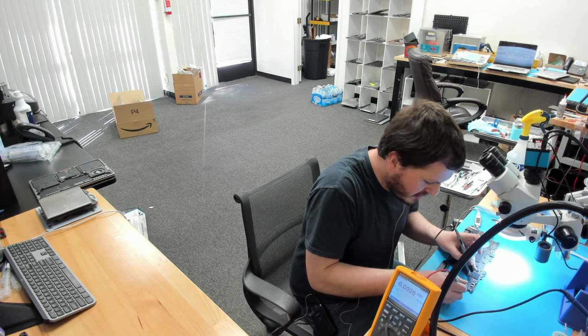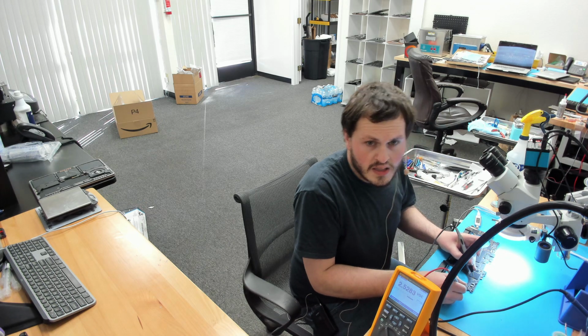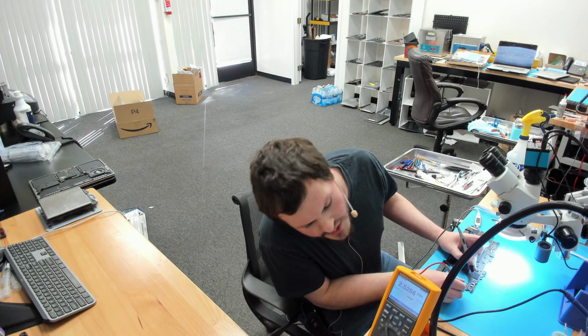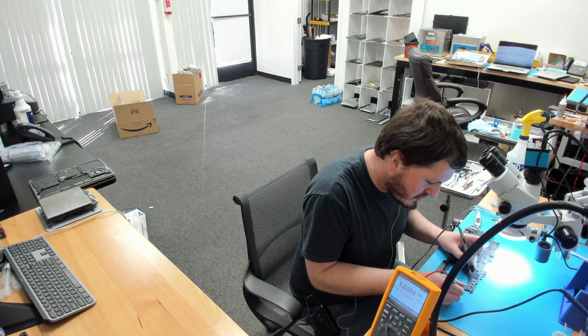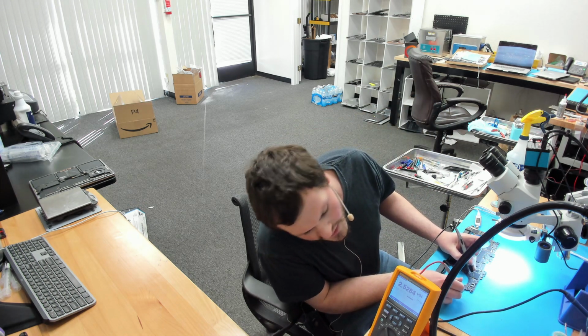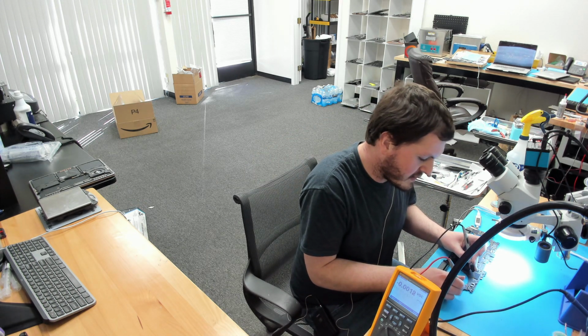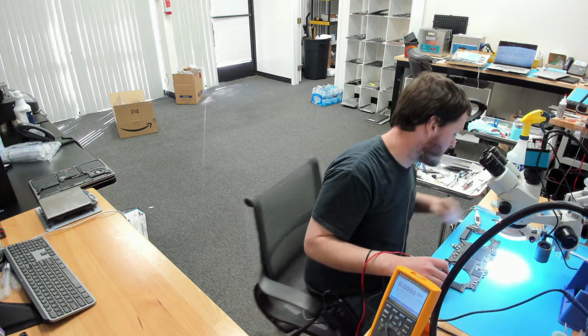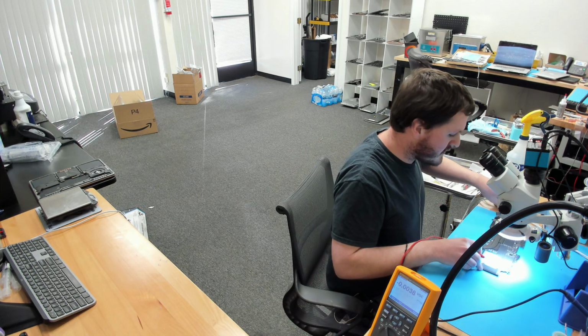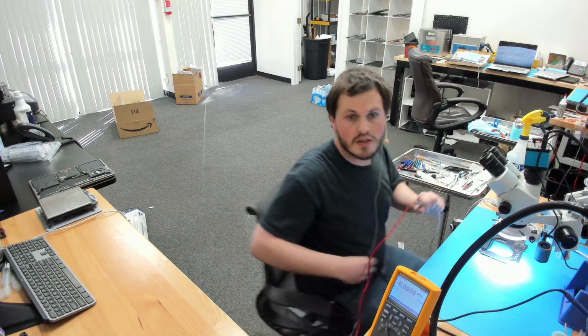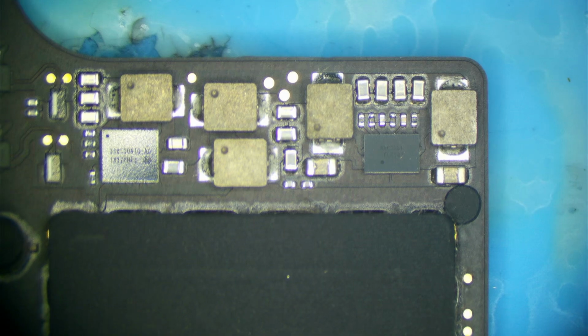So looks like I have 2.5 volts. Good. 2.5 volts. Alright, so this chip is not dead. This chip that I'm measuring right here, which I'm going to show you guys under the scope, is very, very, very common to fail. And it usually fails in a way that ends up sending its source 12 volts into the NANDs, which will kill them and result in complete data loss.